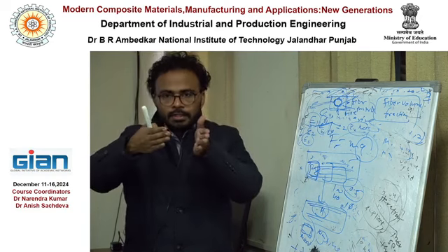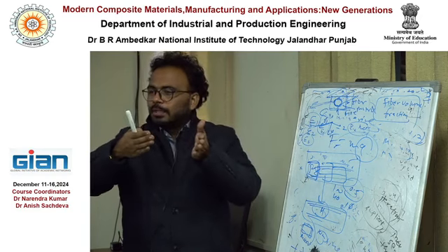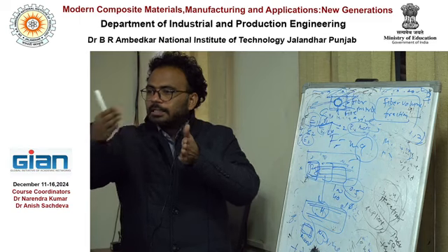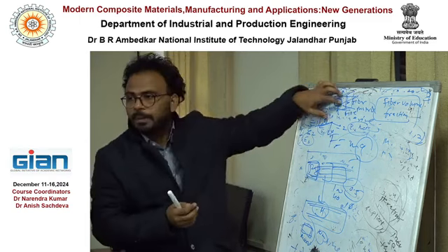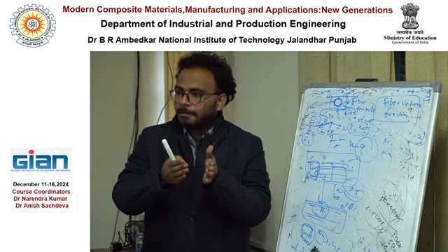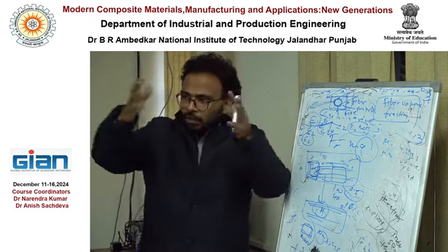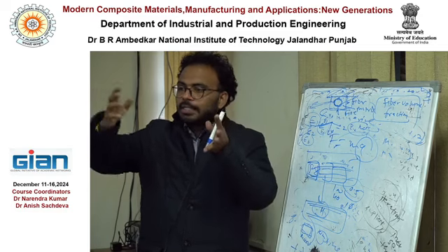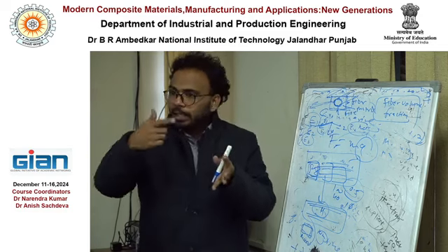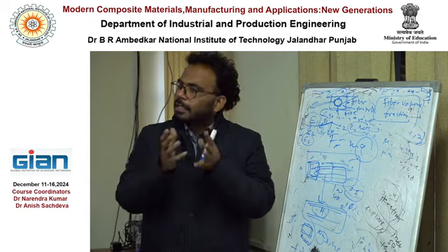So choose the 2 mm. But you think no, only 100 micrometer RVE can cover the repetition. So you think your manufactured part is the repetition of how much dimension? That's the RVE, right? Representative volume element. If you see your macro part, the meso part is the repetition of 10 micrometer. Each 10 micrometer is repeated, so you will create 10 micrometer.